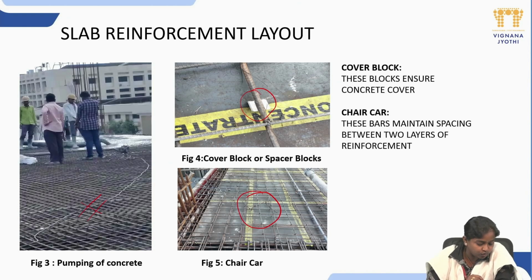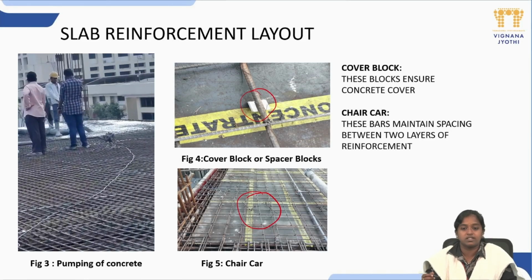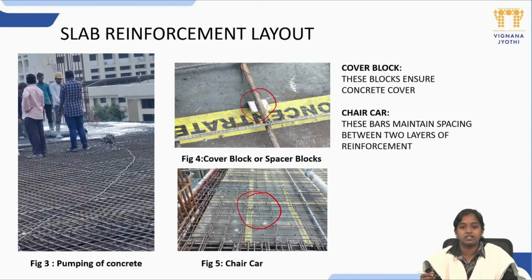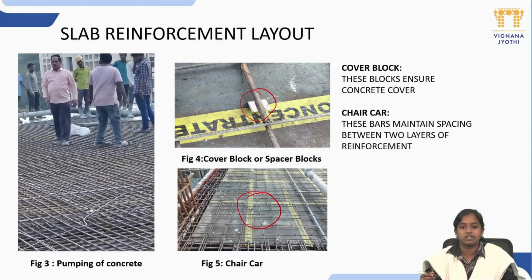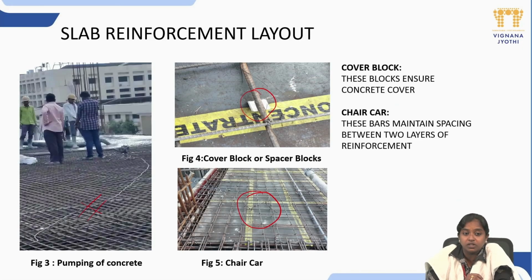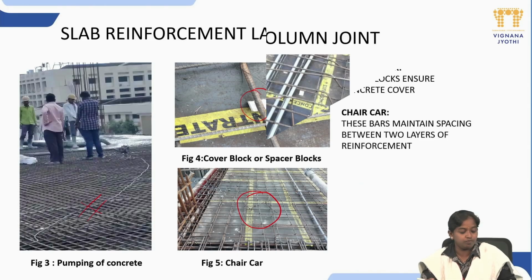And I would also like to show you one more important video in figure number 3, which is pumping of concrete. Once the reinforcement is laid for the slabs, this is how pumping is done to pour concrete into the spaces of the slab. This will ensure that the reinforcement is completely covered with concrete, which becomes your reinforced concrete slab.